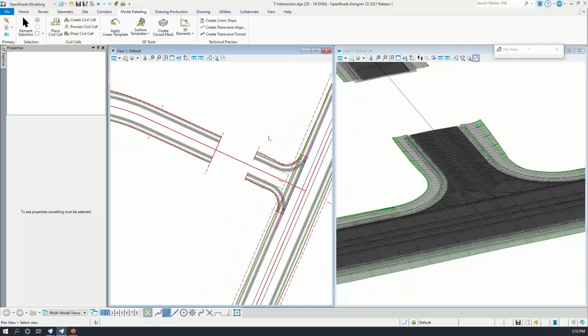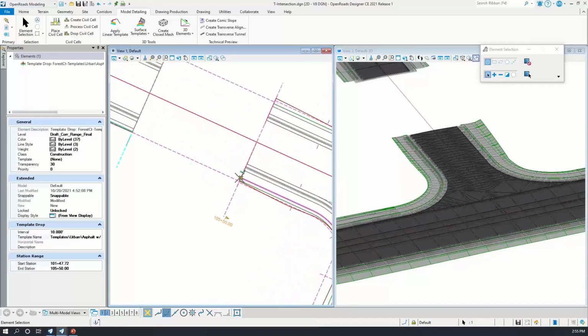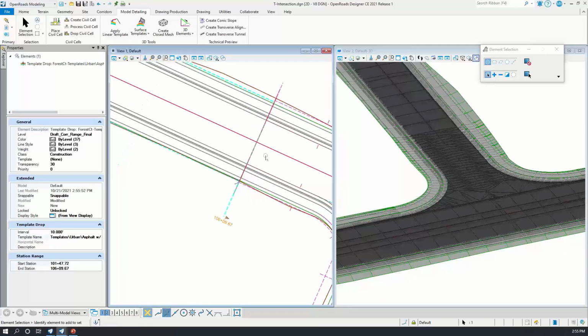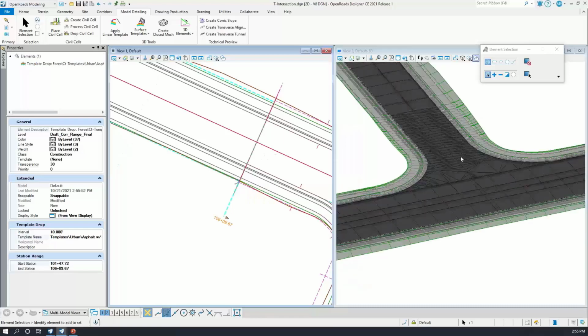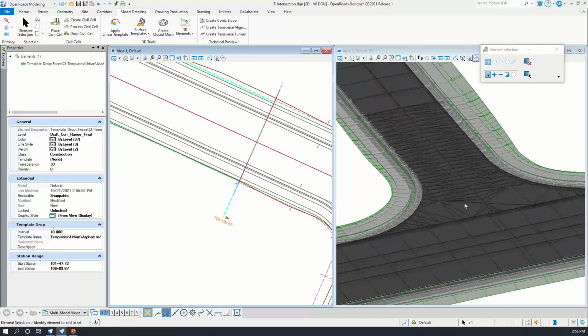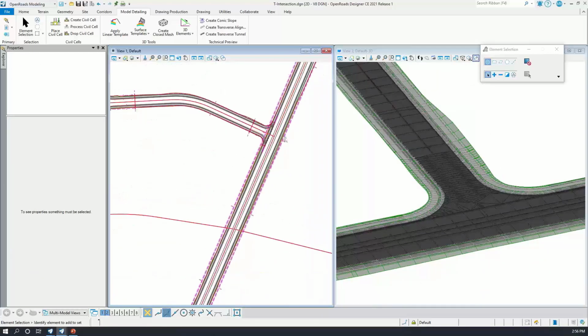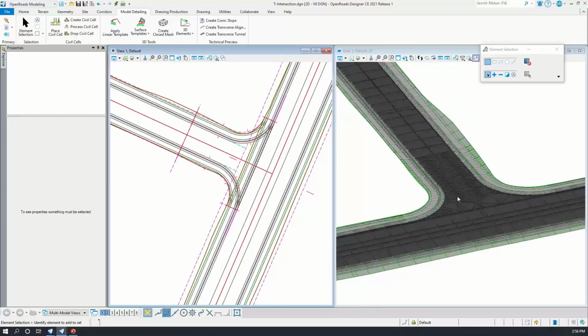Okay, and then one last step to finalize this T-junction or T-intersection is I will literally drag the other corridor and tie it to the civil cell. Right? Are we good? There you go. So just as quick as that, we have managed to model this intersection.